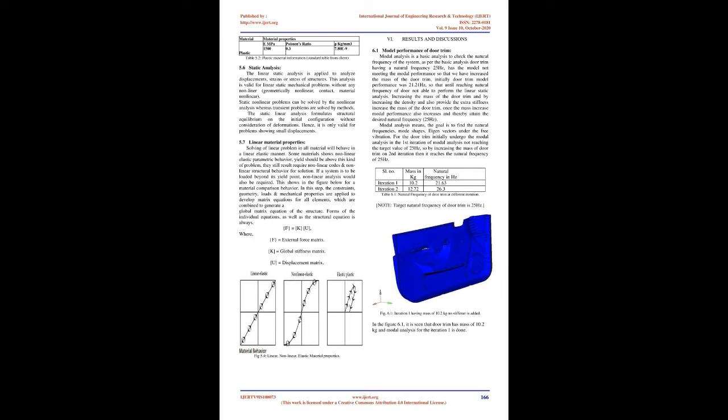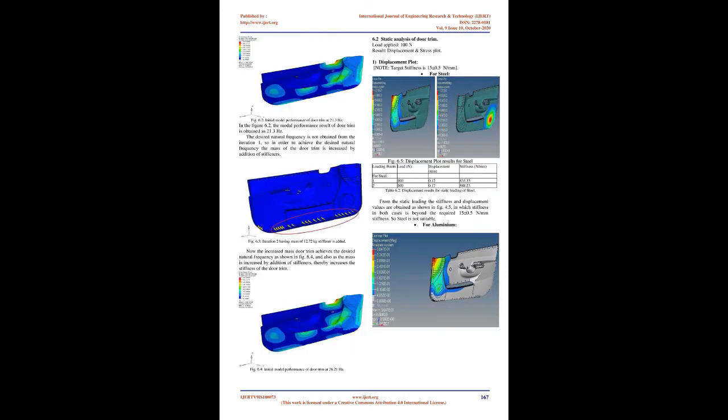4. Objectives. Finite element analysis is a very good tool to reduce time-consuming theoretical work. It is recommended that structural analysis optimization be done for doors. HyperMesh software is used for modal and linear static analysis. The natural frequencies of the door trim should be found, and the free natural frequencies should not be the same as the forced frequencies, so it does not reach the resonance state.